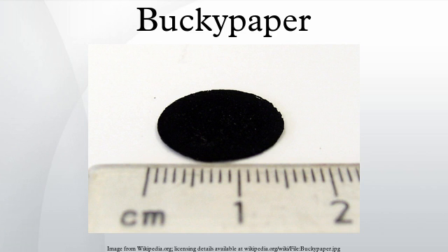By comparison, when a Buckypaper sample was formed from the 1-ton compression of chemical vapor deposition-generated MWNT powder, any application of a solvent led to the immediate swelling of the film until it reverted into particulate matter. It appears that for the CNT powder used, compression alone was insufficient to generate robust Buckypaper, and highlights that the aligned growth methodology generates in situ tube-tube interactions not found in CVD CNT powder, which are preserved through to the domino-pushing formation of Buckypaper.